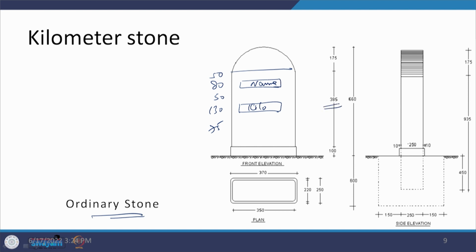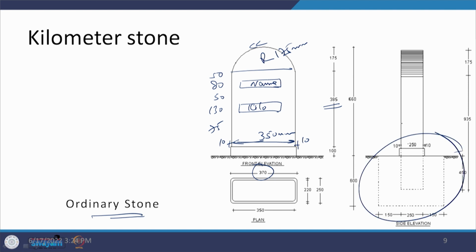But here when you look at this radius of a semicircular section, then this one is 175 mm. So, obviously, in that case if we are looking at this size, then this comes out to be 350 mm, with again 10 mm offset on both the sides, it becomes 370, and the same way at the bottom which is being embedded, the things are being placed.